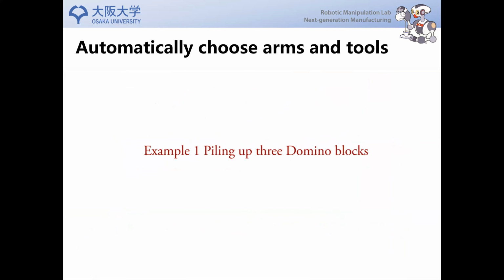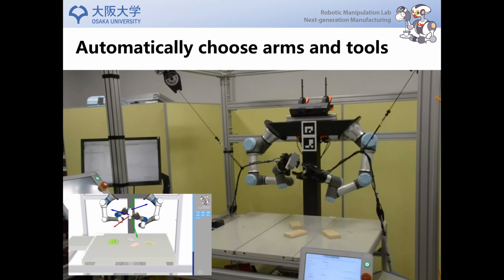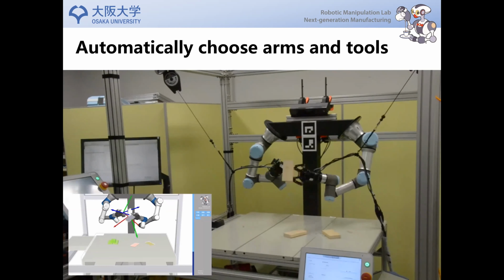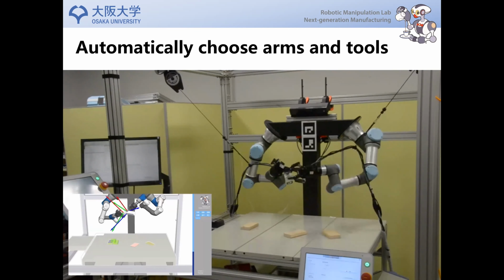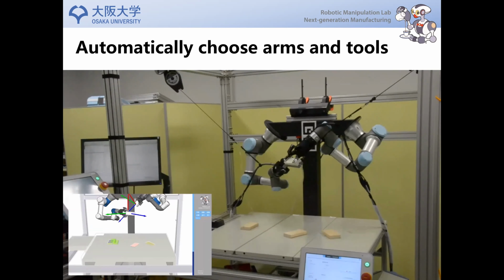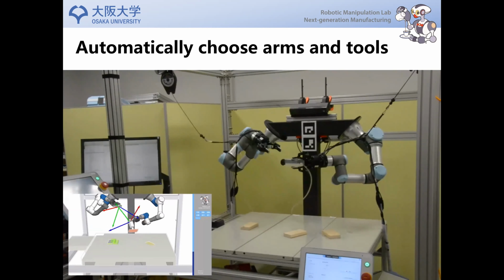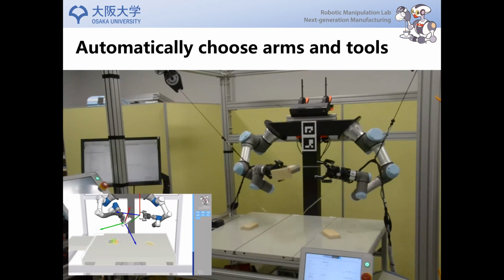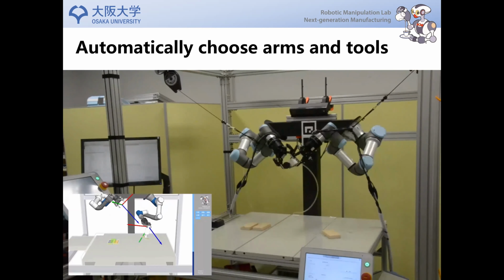First is to pile up 3 domino blocks. According to the combined task and motion planning, the robot will determine whether to use a handover or not. In this case, the robot is doing a handover, and for example, in this case, it's doing 2 handovers to make sure the suction cup tool is correctly oriented, so that the robot can use it to reach the wooden blocks.